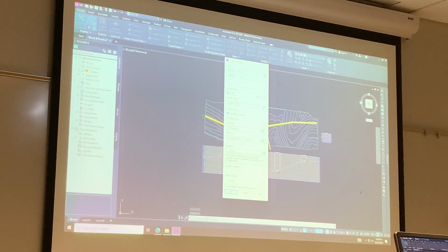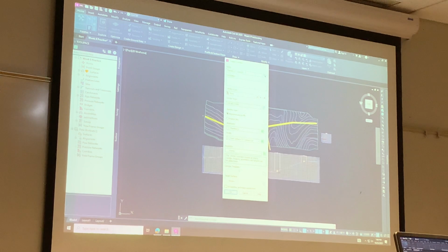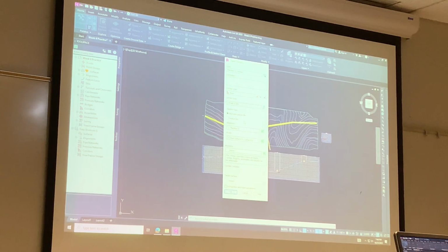You can give it a name or leave it as the default. Normally it would default to something else, but because the file I put on the canvas has this preset, that's what it's set to. Then there are a few things we need to select. Go to alignment and check the main line, making sure we choose the right alignment for the corridor we want to create.